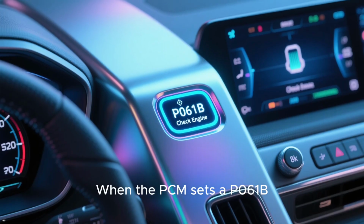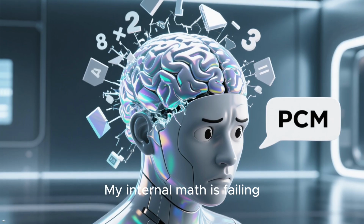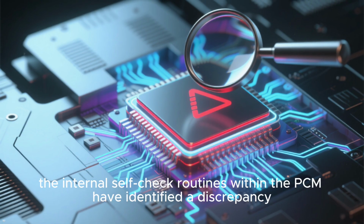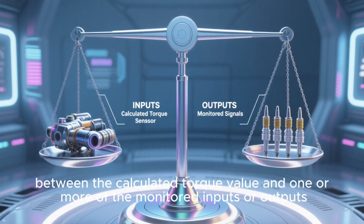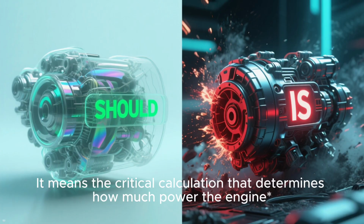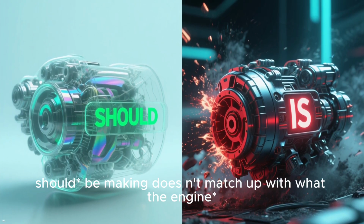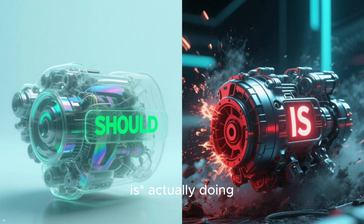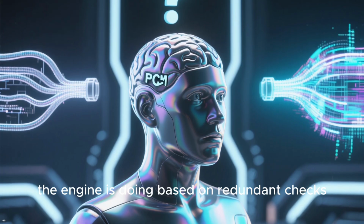When the PCM sets a P061B, it's essentially saying, my internal math is failing. Specifically, the internal self-check routines within the PCM have identified a discrepancy between the calculated torque value and one or more of the monitored inputs or outputs. It means the critical calculation that determines how much power the engine should be making does not match up with what the engine is actually doing, or what the PCM thinks the engine is doing based on redundant checks.